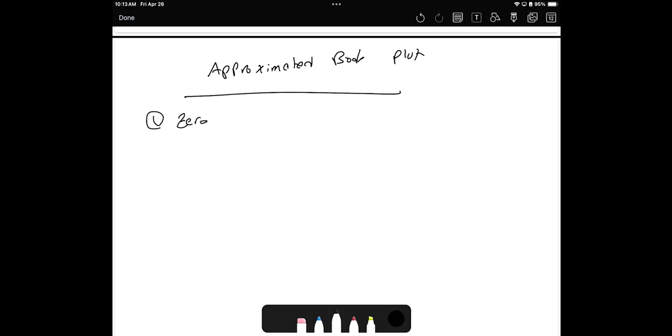So we will try to make the transfer function written as 1 plus j omega over omega c. Omega c is a constant, sometimes called the threshold frequency or cutoff frequency. So we will convert, substituting every s by j omega, then dividing by a constant, omega c. How we will do that, we'll talk later, but now let's see the effect of the 0.